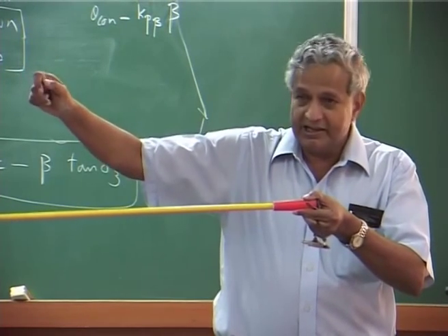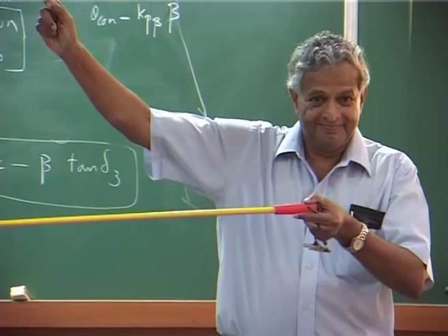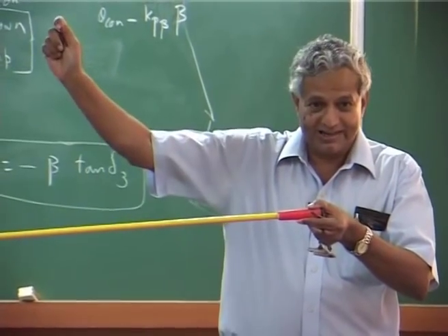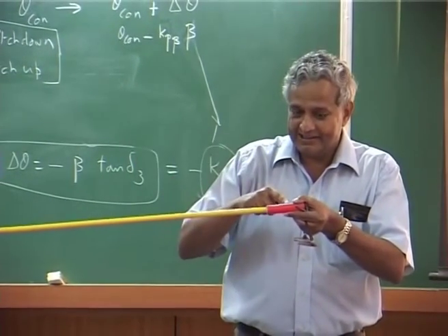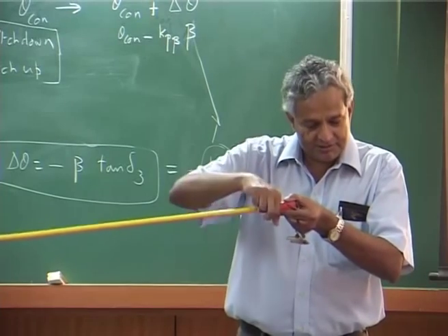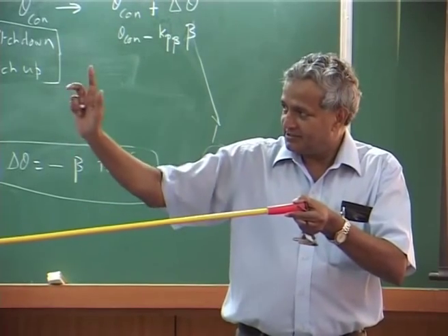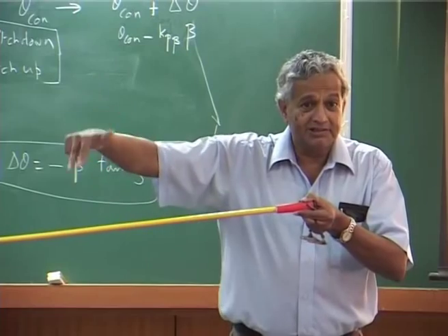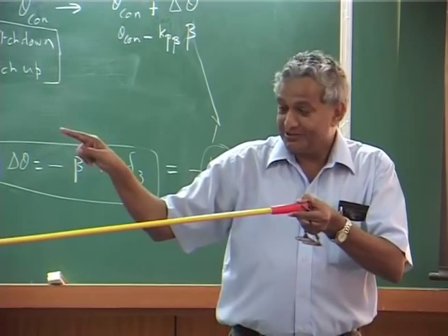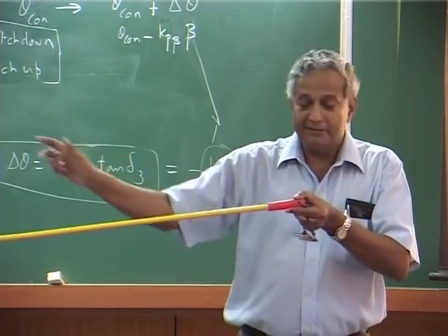Now, any lift will give, lift force is acting on the blade, the pitch link is here, pitch bearing. If the lift increases, this will give a pitching moment with respect to how far I am back.